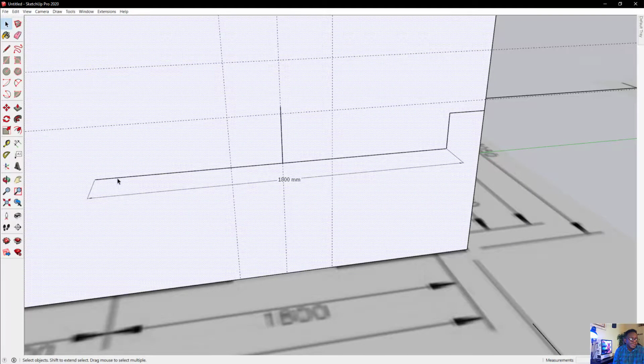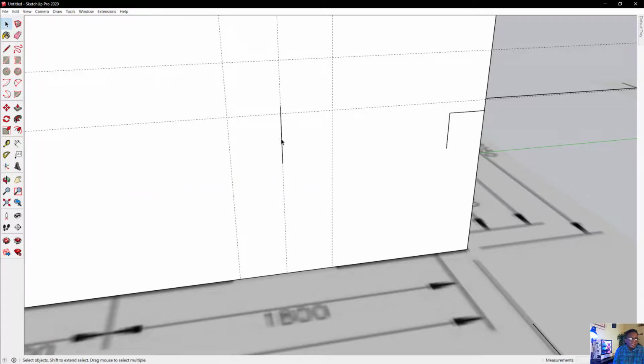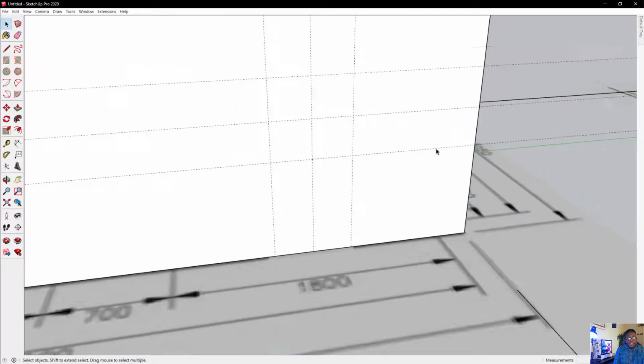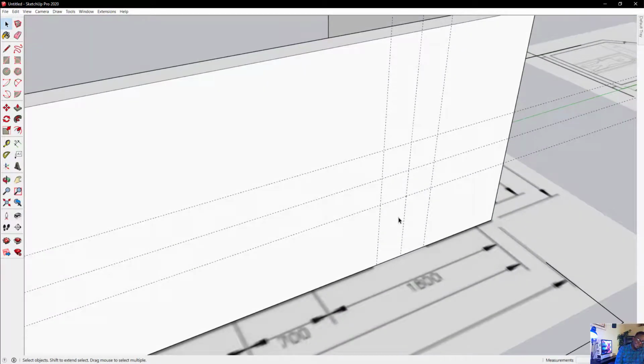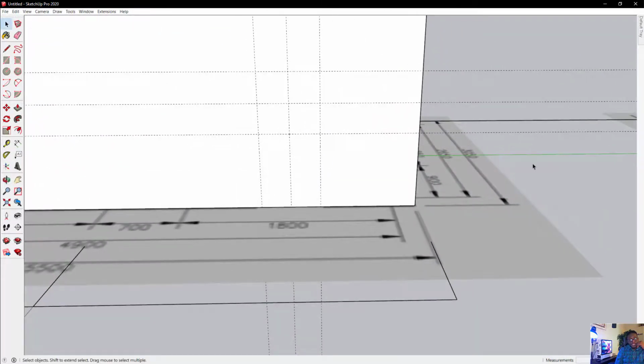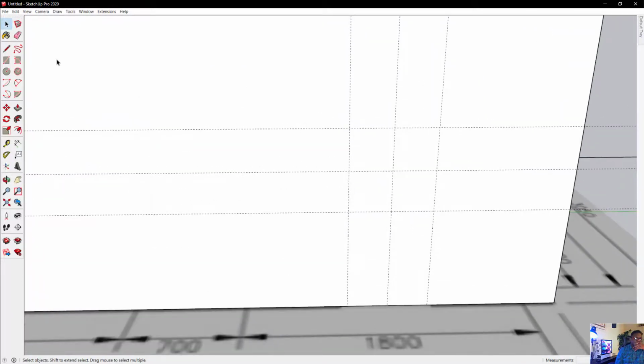So notice that these lines that I put in, I always try to remove them when I'm not using them. What you can keep are the measurement lines, because they are not impacting your drawing. But once you use the pencil tool, it's going to cut your polygons. Now, it's probably higher than this, but this is just an example that I'm giving you guys. Besides, you can actually move this window when it's done by using the move tool. If the window was supposed to be higher, you could actually move the window higher.